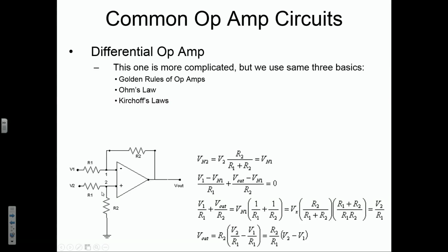It's basically the voltage between node 2 and ground across resistor R2. Remember, it starts to look like a voltage divider, right? This is like our voltmeter resistance here, and this is our input resistance. So this is our gain, R2 over R1 plus R2.